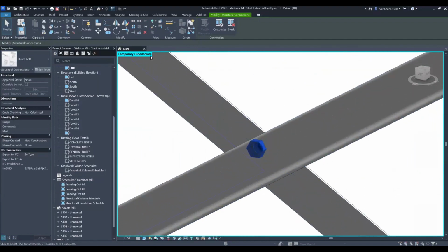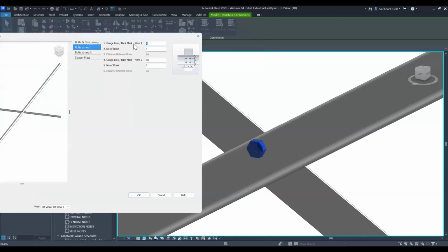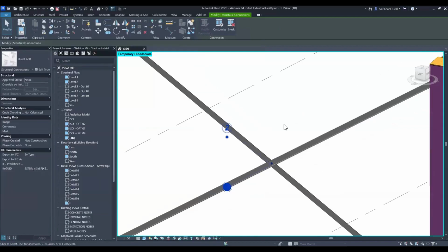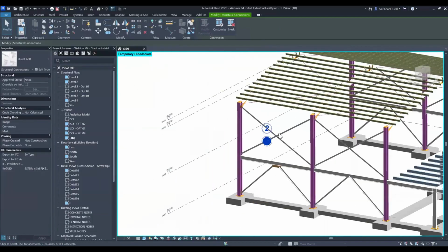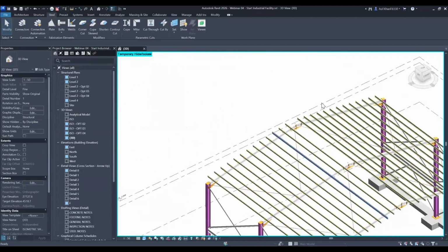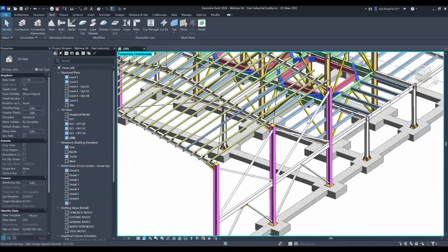Now I'm going to the parameters, and over the parameters, I'll change the bolt distance 40 instead of 70. I'll go for 45. If I just change this 45, as you can see, it will come up at the center. Press OK, press apply, and there it is. Now, if anyhow the structure changes, the connection is going to adapt automatically. Now, the last bracing I'd like to talk about, which is this one, which is basically a tension brace applied over here.